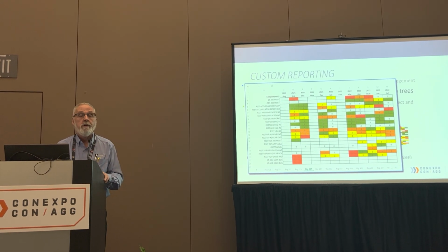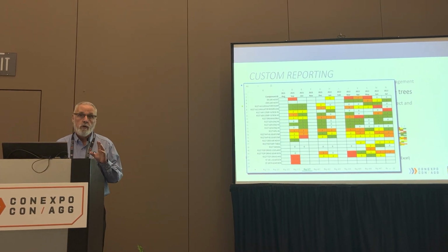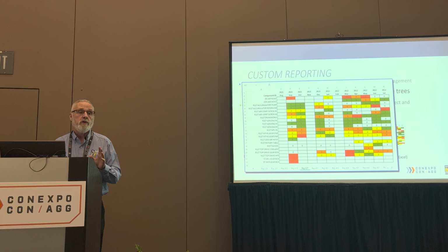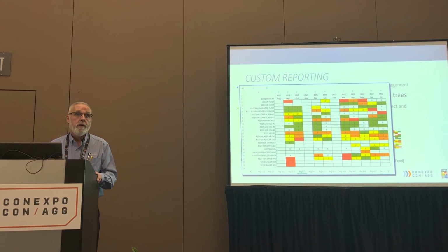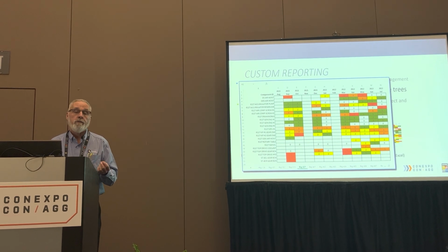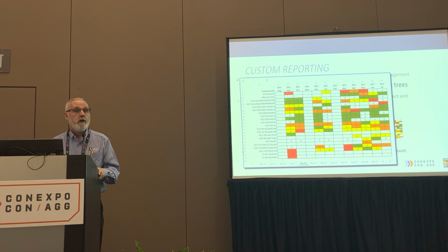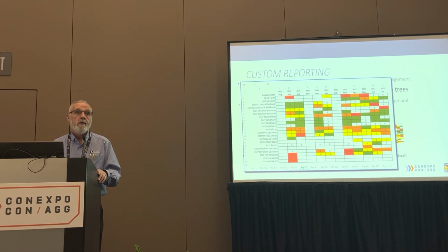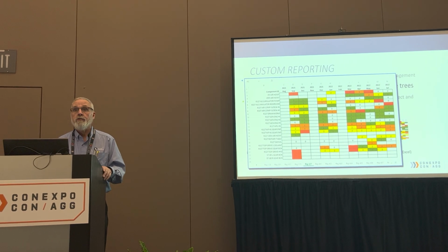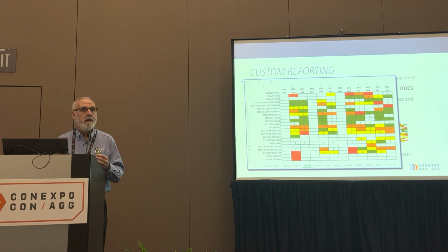High severity reports, folks, are terrible because if you ignore them and you don't schedule them right away, that equipment's going to schedule time for you because it's just going to break down, and now you're faced with reactive, unscheduled maintenance, which is going to cost you 2 to 10 times higher to repair, greatly increases your loss in production. We always want planned, scheduled maintenance.